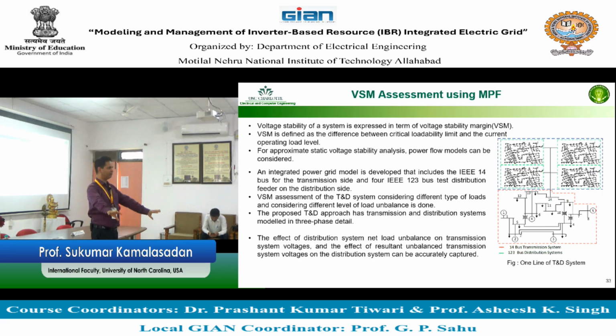So frequency is what we call global, dependent on several different factors. Angle is what we call local, dependent upon each generator or each bus. So you need to study local disturbance and local stability, and at the same time find out globally whether the system is stable. That's why we study them differently.